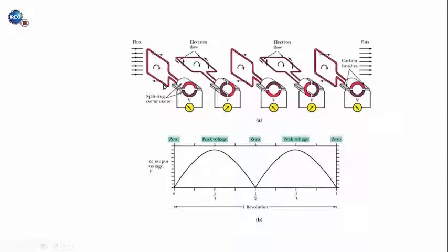And so imagine that this conductor is rotating with its commutator and brushes. When this part of the conductor connected to the red part of the commutator is moving from left to right through this flux field, none of the flux lines are being cut, and so the induced voltage will be 0 volts. But as we continue to rotate clockwise, this part of the conductor will be moving down through the flux lines, and when it moves down, that is perpendicular to the flux lines, and that's when most of the flux lines are being cut the quickest.